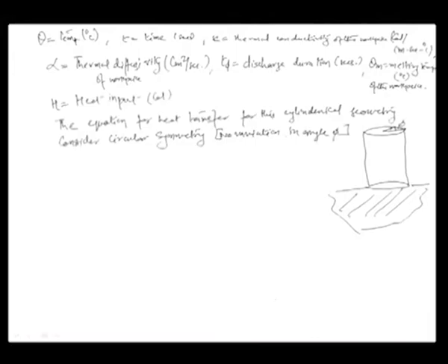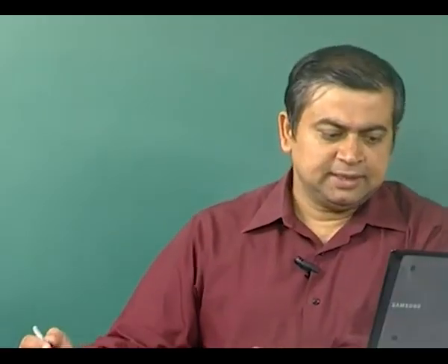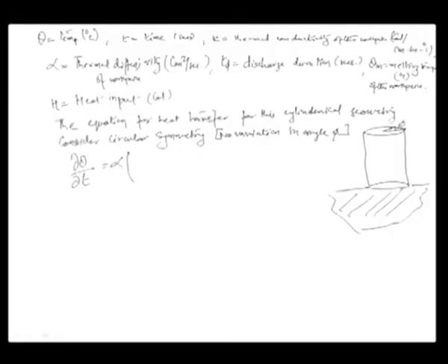Then the way that temperature behaves in time, d theta by dt, is represented as thermal diffusivity alpha times the second derivative of theta with respect to the radial distance r, plus 1 by r del theta by del r, plus del 2 theta by del z2, and z is basically the variation in this direction. This is the z direction, this really is the r direction, and this exactly is the angular variation, okay.